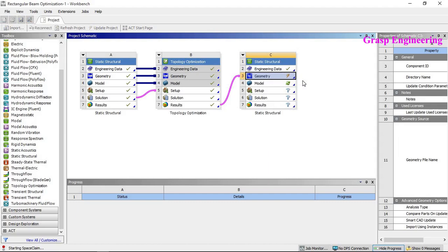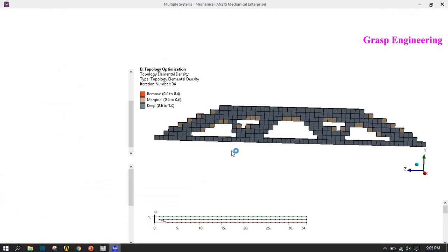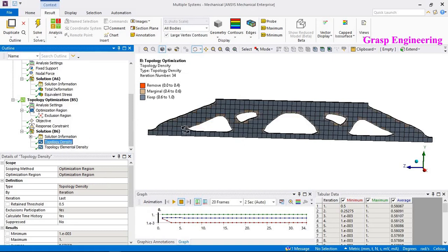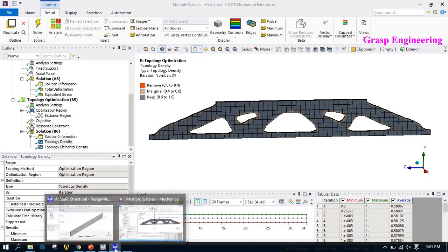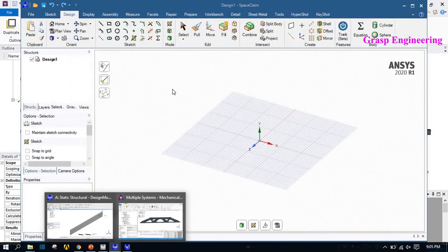Basically what it does, the STL file, if you remember we saved that STL file, will be carried forward in SpaceClaim, and the shape will look like this. For this you will find the facet geometry, and we can do a fine tune further in order to perform.